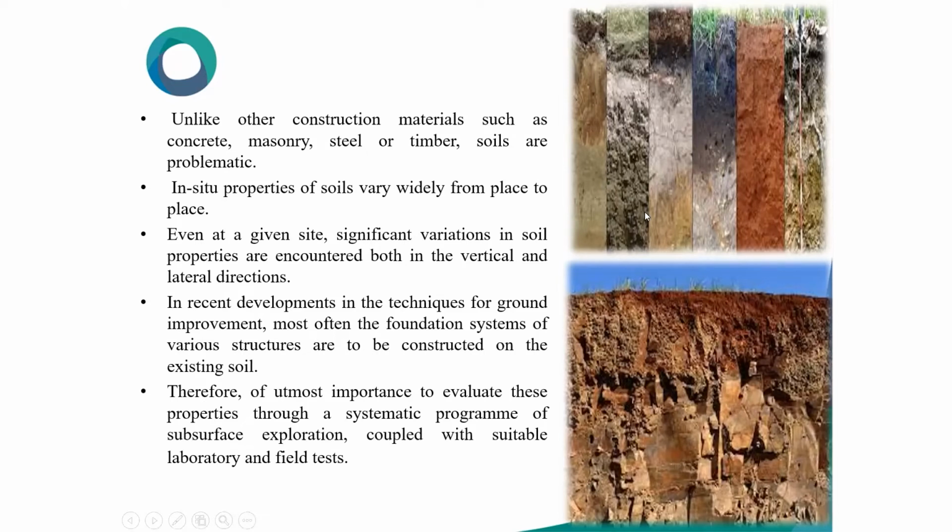Unlike other construction materials such as concrete, masonry, steel, or timber, soils are problematic. In situ soil properties vary widely from place to place. See here, what soil property are you getting? Here you won't get it. Here it looks soft, but when you go deeper and deeper, the properties are completely different.